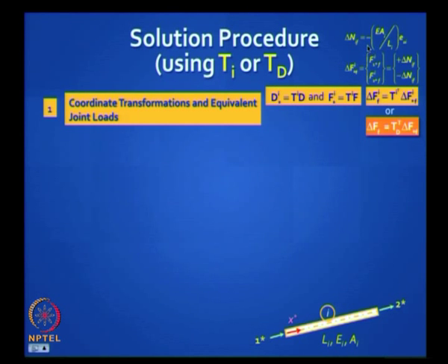It will be minus because it is going to go into compression. The axial stiffness is EAi by Li, and epsilon naught i is the thermal strain, that is L alpha delta T for the ith element. Is it clear?